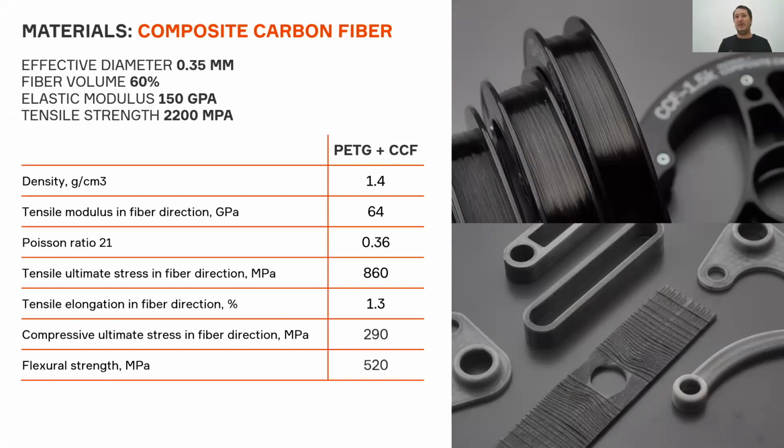When we print it together with plastic, the fiber is a little bit squeezed to an elliptic shape, and a little bit of plastic is added around the fiber. So the single fiber print has a width of 700 micron. But if you want to print a thin wall, the fiber will always be surrounded by a thin plastic shell.